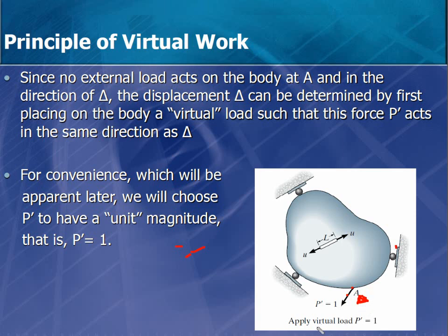So applying a virtual load, this load is virtual, and we're going to use 1 kilonewton for the purpose of easy calculation. It will be convenient for our calculation to use 1. It can be kilonewton, it can be kips, any units that you have. One unit load, we will apply it here. Now this load is going to create internal load.